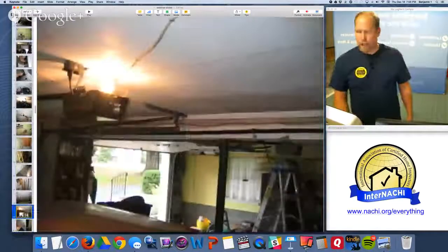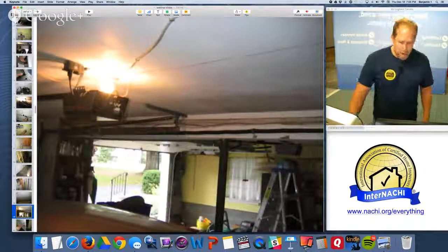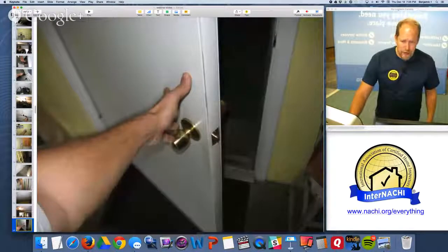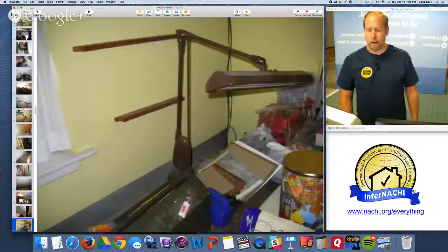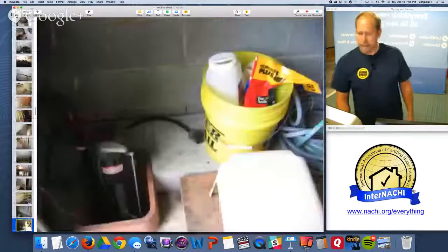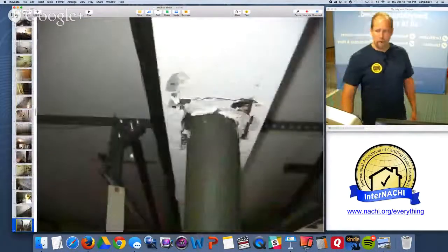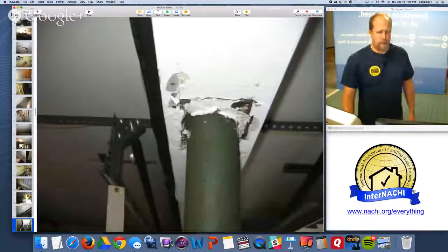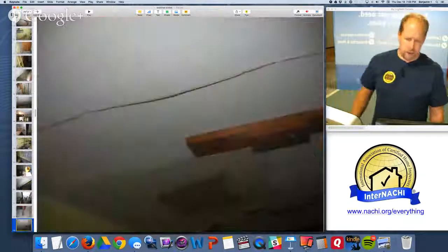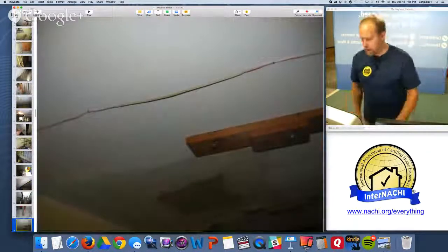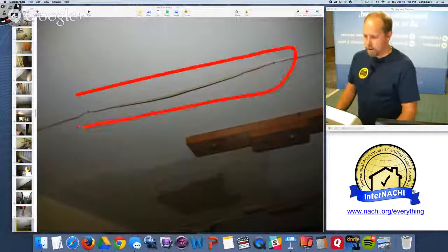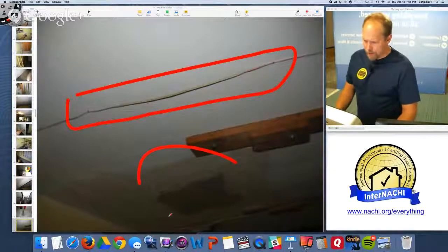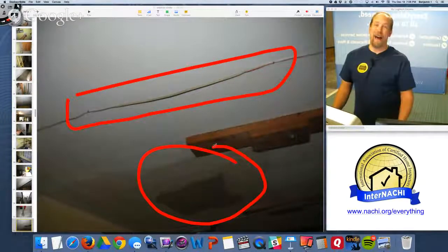garage. A lot of improper wiring, a lot of wires just hanging with a staple and some duct tape and twisted around. The fire door is not to modern code, but at least has some metal on it. So I'm identifying that, the firewall. I take a look at the main beam, the center beam, and the post, how it goes into the concrete. So we have improper wiring, right? And we also have a patch here, typically a bathroom above the garage ceiling.